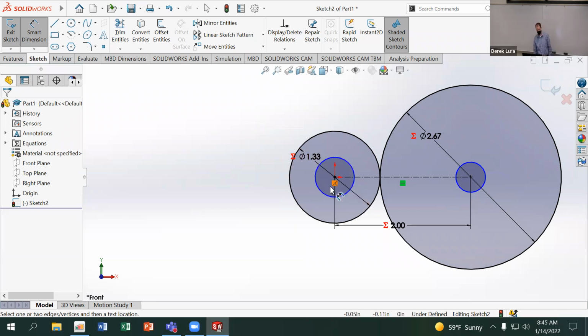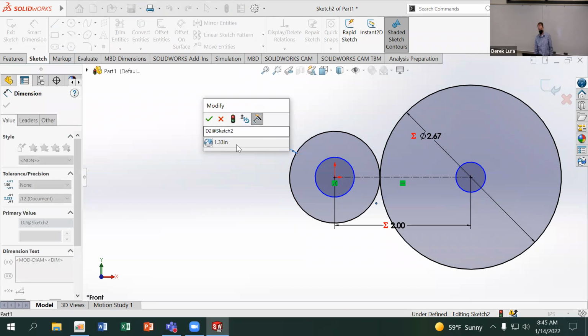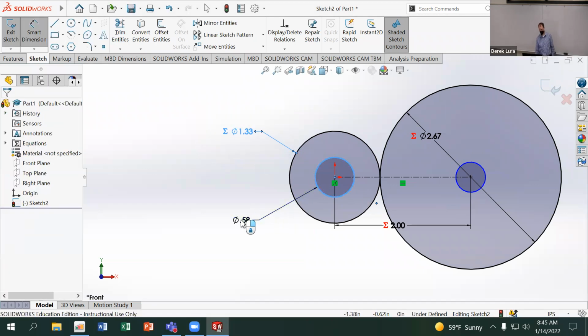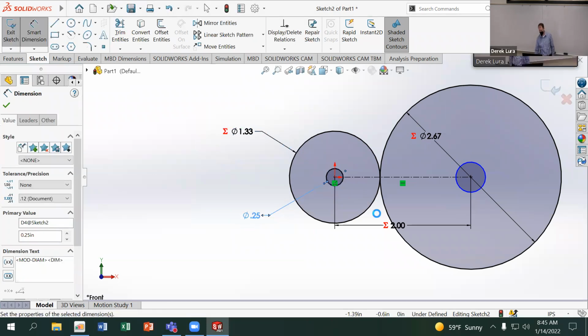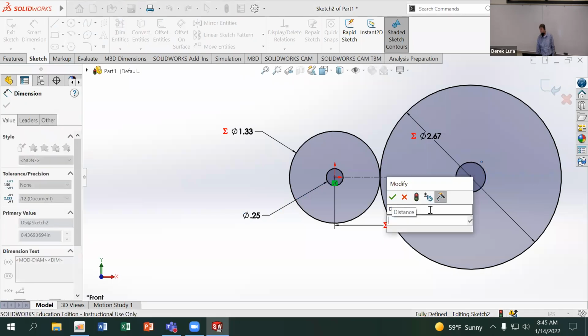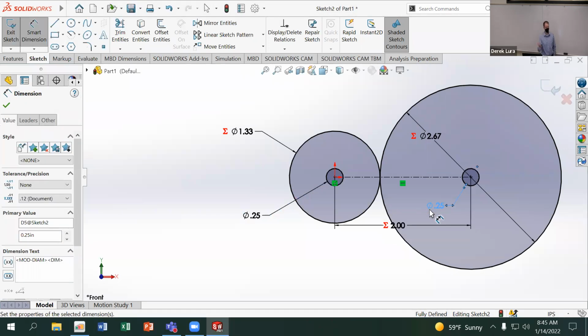Yeah, Isa. What's the diameter on this one here? This is my diameter in. So you should be saying equals to, quote, diameter in. And then the one on the right is my diameter out. And then for the center one, I'm just going to use a 0.25 inch diameter because I don't really care what the size of this input hole is. I could have specified that in my global variables as well. I was just trying to keep this simplicity here reasonable.